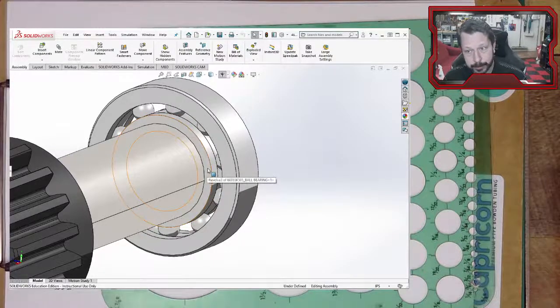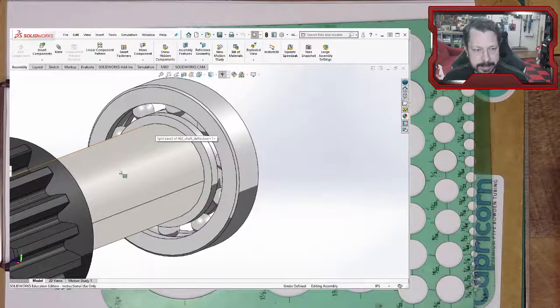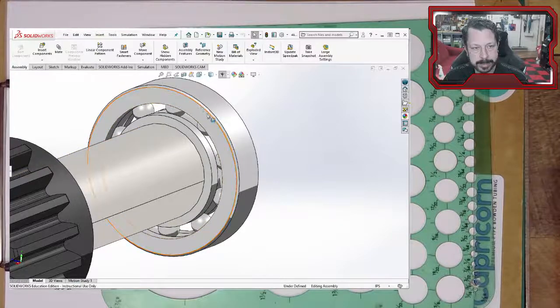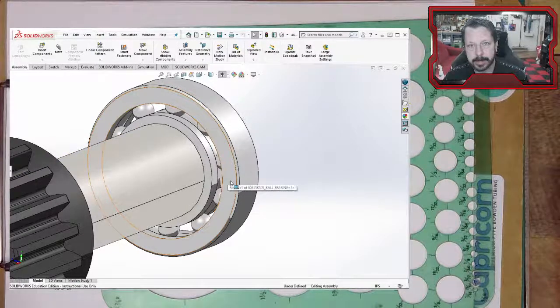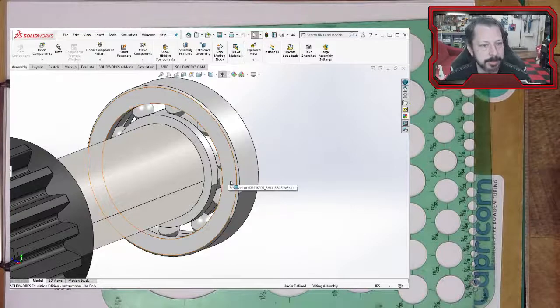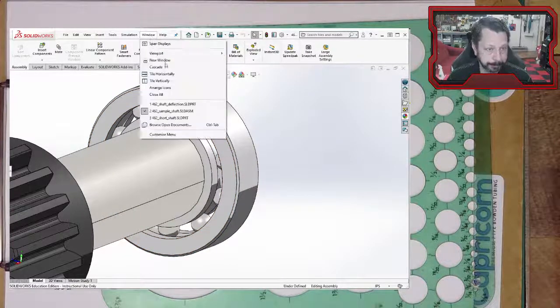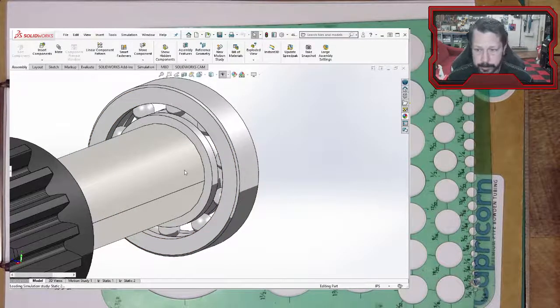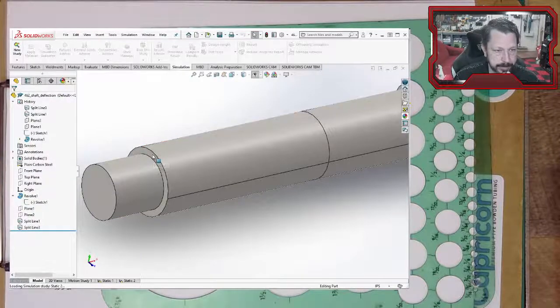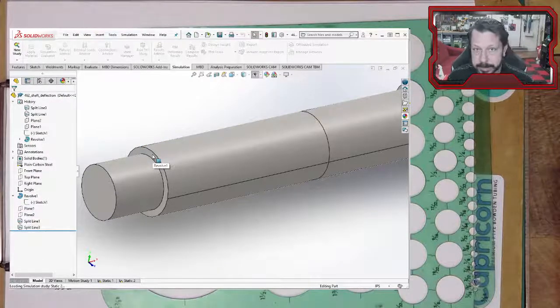We'll talk about ball bearings at a later time also, and mention that again. But if I had this shoulder so large that it was making contact with the outer race, then I've locked up my bearing and it can't do what it's supposed to do. So you do have to be careful with that. Let's go back here. So there's the little shoulder, and again, I can make that somewhat larger, but not a lot larger.